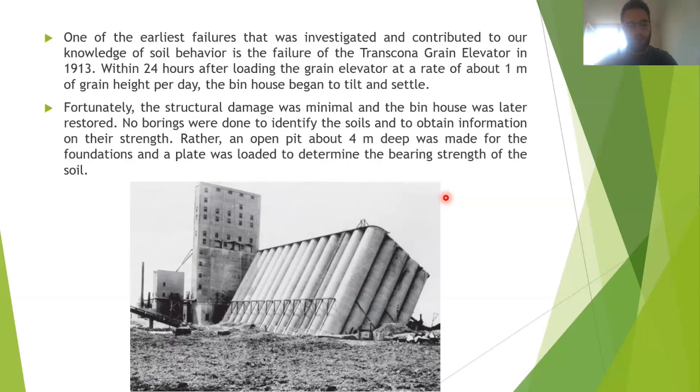Of course, but still, with the investors, you're going to fight about the soil investigations, and you need to be really safe there. You need to know how to decide when to do boring, when the open pit is just okay, and when geophysics are still just okay. So the thing is, this is a big structure. You see 1, 2, 3, 4, 5 floors there. That's 15 meters plus those foundations, like a 20 meter structure.